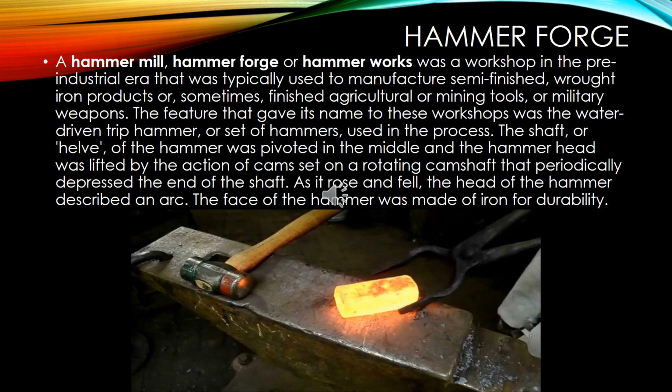Before the development of effective methods of steel making and the availability of large quantities of steel, wrought iron was the most common form of malleable iron. It was given the name wrought because it was hammered, rolled, or otherwise worked while hot enough to expel molten slag. The modern functional equivalent of wrought iron is mild or low carbon steel. Neither wrought iron nor mild steel contain enough carbon to be hardenable by heating and quenching.